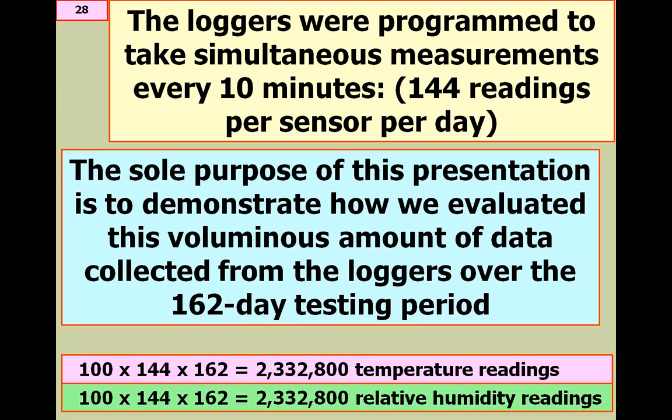The reason this is important to us is because in our building envelope performance investigation, we're not interested specifically in relative humidity. We're not interested specifically in temperature. We're interested in water, actual water. How much water, or in this case water vapor, how much water is there? If there's more water in one location than another, then very likely the area that has the most water is a major player in the water damage that has occurred, whereas the area that has least water is a lesser